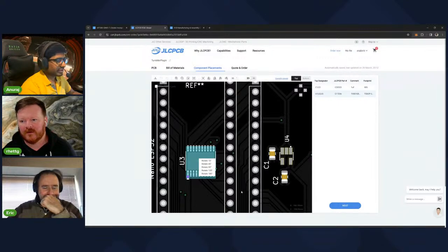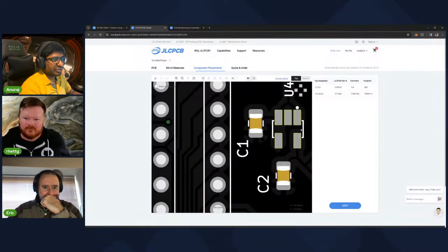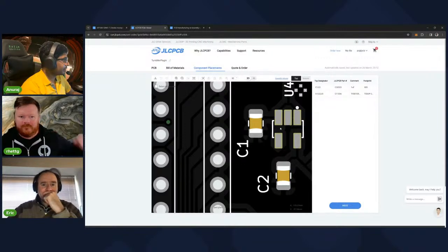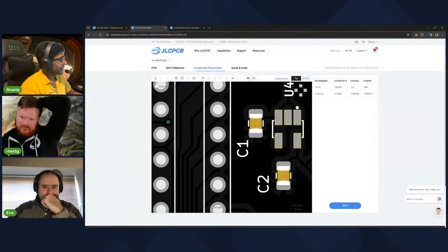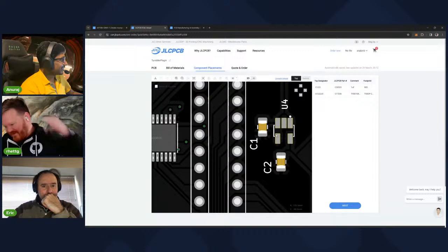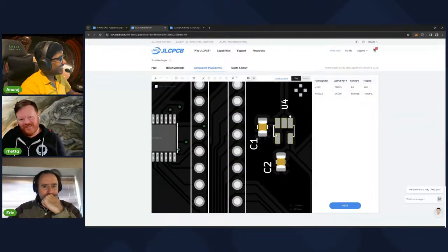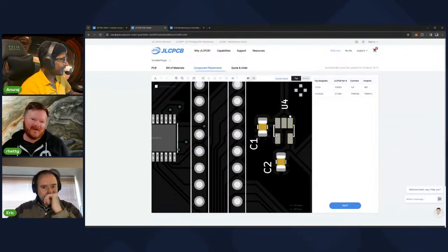Oh, I see. Cool. And for SMT components this is really important, because after manufacturing, most people wouldn't think that there is a mistake in orientation, and then it becomes really hard. The hardware guys will assume they have done it correctly, the software guys will assume they have done it correctly, and nobody thinks there could be an orientation mistake in the manufacturing itself.